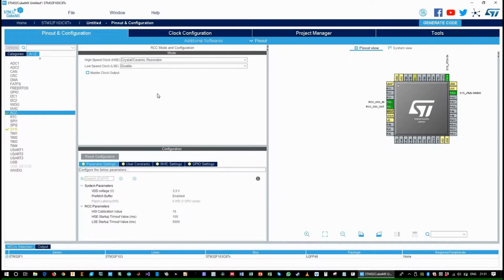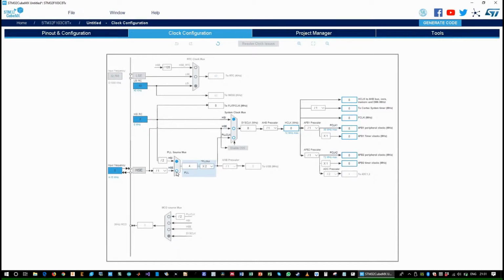And now that we have the clock configured and enabled, we're going to configure the clock. We're going to click on high speed external oscillator, then on the PLL clock. We're going to notice that the maximum speed of the microcontroller is 72 megahertz. In order to achieve 72 megahertz, we're going to modify our PLL multiplier. So we're going to multiply times 9 to get the 72, because it was not being divided by anything, it was divided by 1. So the 8 megahertz divided by 1 gives us 8, and then 8 times 9, 72 divided by the prescaler being at 1 gives us 72 megahertz.